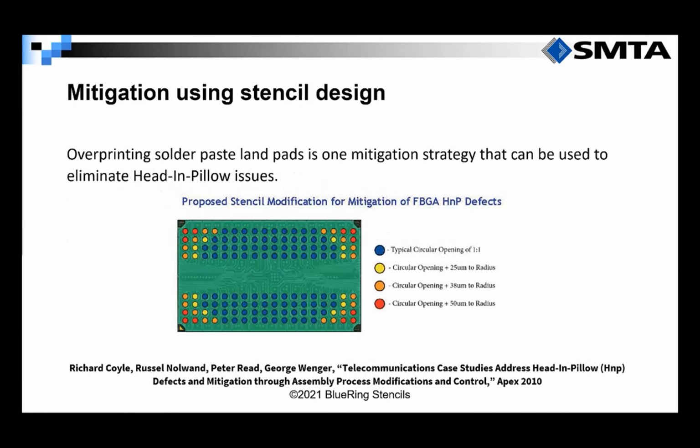Please remember, it's critical to share the component drawings with the stencil manufacturer if the PCB design doesn't include the modifications. In addition, and I say this all the time in these types of presentations, if you only share the paste Gerber layer with your stencil house, they can do very little to proactively design your stencils. It's important to understand the more information you provide at your stencil order, the better the design can be.